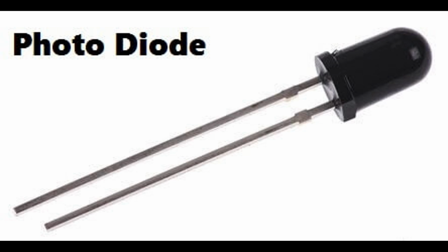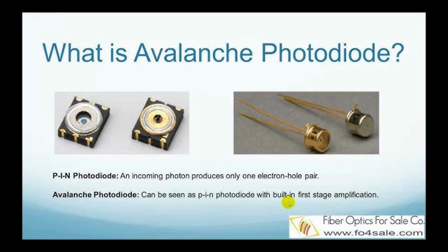Different materials are used to optimize responsivity for specific light spectra, e.g., silicon for visible light, germanium for infrared light. 2. Dark current. Definition. Dark current is the small current that flows through the photodiode even when no light is present. Cause. It is caused by the thermal generation of electron-hole pairs within the semiconductor material and increases with temperature.